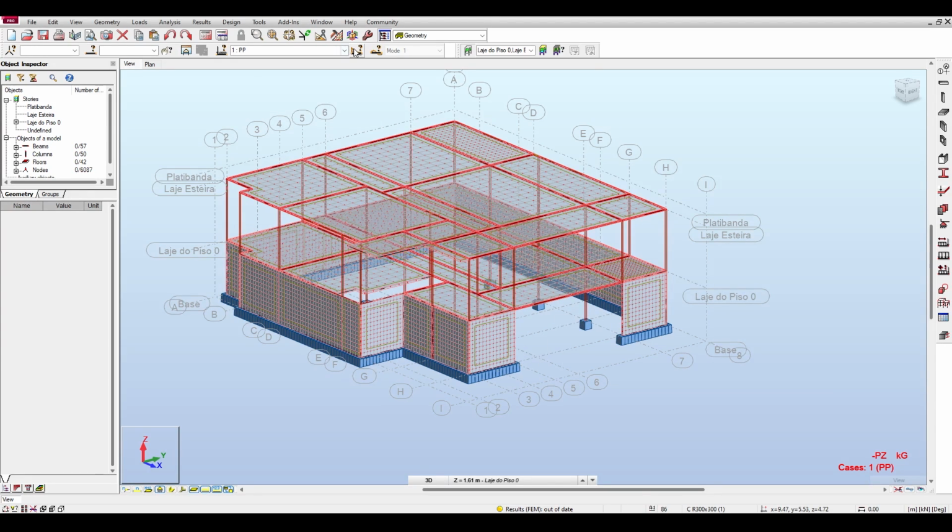Now for the load cases, there were multiple load cases. I deleted most of them because I want to focus on the modal analysis today. You have the load case PP. Now I think this is Spanish. I don't know exactly what this means, but I can only guess. I think that this load case is the self-weight only, and you can see actually that he only has self-weight here. And you would think, wait a minute, why does he have a load case for self-weight only?